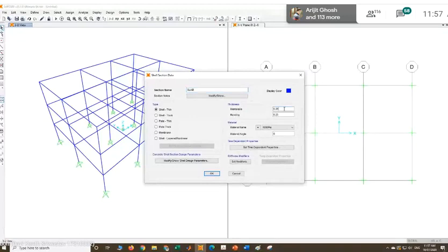We have given a thickness of 250 mm. Slabs are generally kept linear, so it is kept elastic. So slab needs to be designed manually, and then slab only needs to be modeled in the structure. We can model a beam and column for nonlinear loads also. It can, but slabs are generally kept elastic, because I will explain why we go to elastic design rather than non-linear.